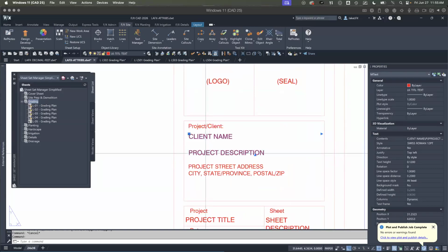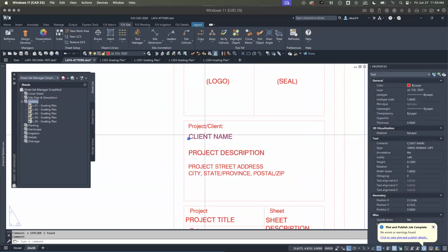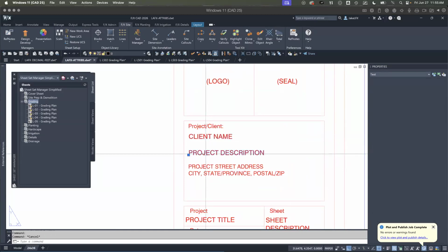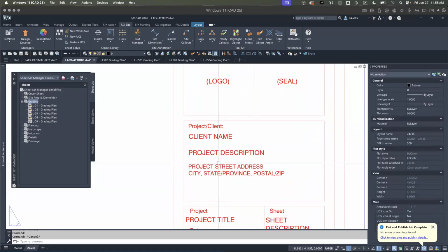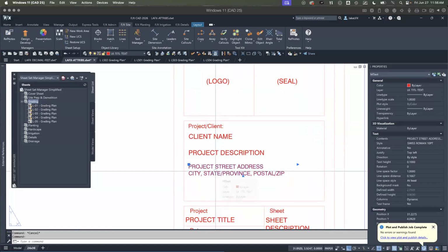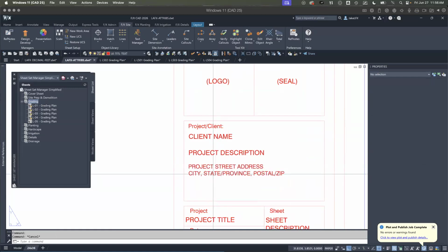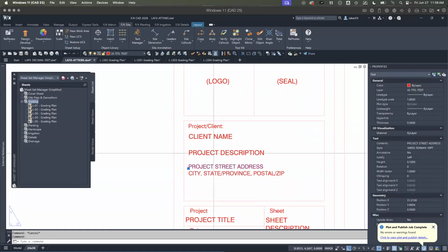But MText you can simply explode. It does turn it into text, but it breaks them out into their own line items. So I don't need to move things away, copy them and remove stuff. I can just explode those and get them into their own line items.